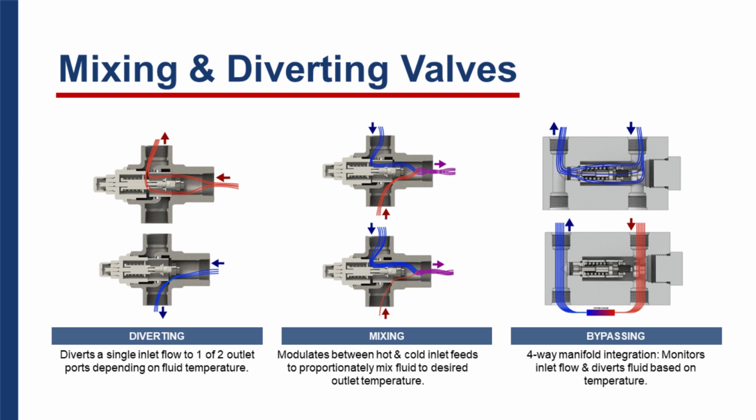Now as the actuator heats up, it's going to extend out and it'll start modulating the spool, and so it'll lower the spool, choking off that cold port when it gets up to the target temperature, and now your flow has been diverted to the upper port. It's still coming in the common right-hand side inlet port.